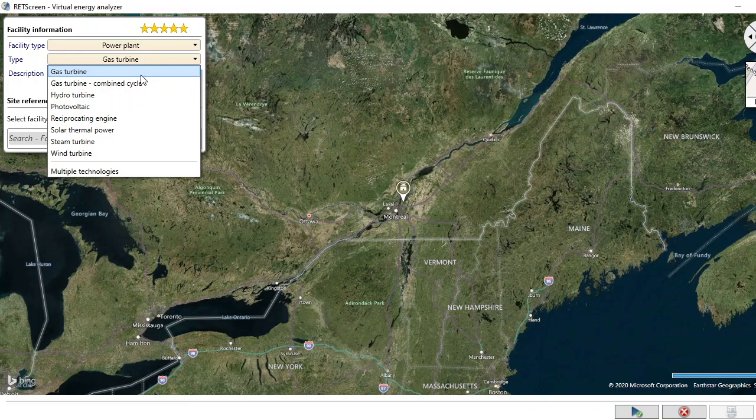So we do have gas turbines, we do have gas turbine combined cycles, which is combined cycle power generation, which uses heat recovery steam generation, in which we first burn the gas, our working fluid, and then the residual or flue gases are used to raise the temperature of the water or to convert it into steam. We produce steam and we then run it in a steam turbine. So that's a heat recovery and steam generation system, and you can call it a next level advancement in gas turbine systems.